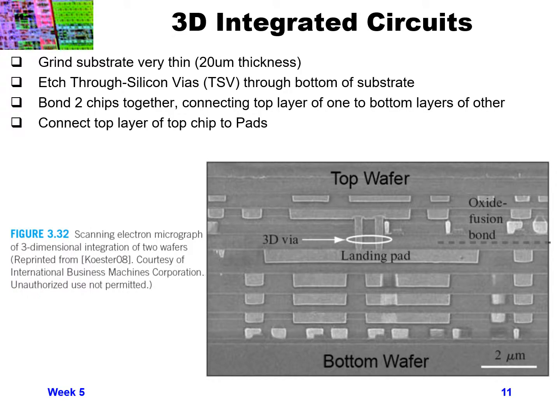As long as we've designed our chips so that the bottom layers of metal of one chip have specialized pads that connect through these through silicon vias to the top of the other silicon chip, then in effect we have a landing pad at the top of one chip and a via connection pad for the TSV vias on the bottom of a different chip.